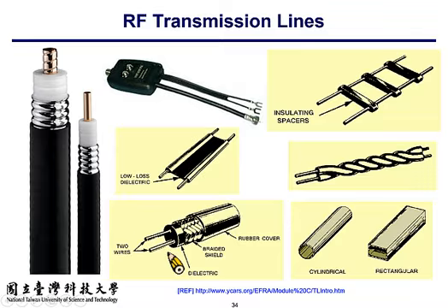This one is twisted wire. It is also a two wire line, but twisted. Its purpose is to prevent signal leakage or interference; we will discuss later why it is done this way. This is called twisted pair wire. The purpose of this structure is meant to prevent the so-called EMI and EMC issues. EMI refers to electromagnetic interference.